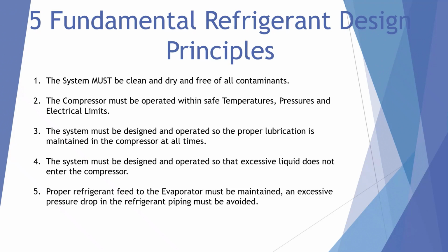3, the system must be designed and operated so the proper lubrication is maintained in the compressor at all times. 4, the system must be designed and operated so that excessive liquid does not enter the compressor. And 5, proper refrigerant feed to the evaporator must be maintained. An excessive pressure drop in the refrigerant piping must be avoided.